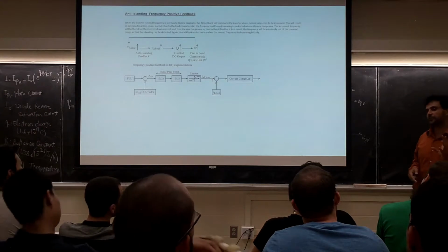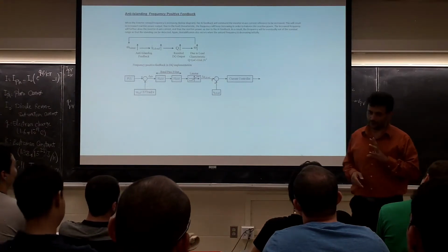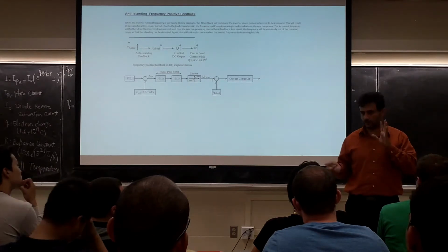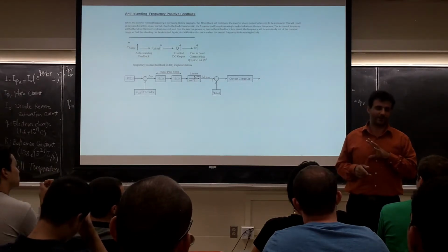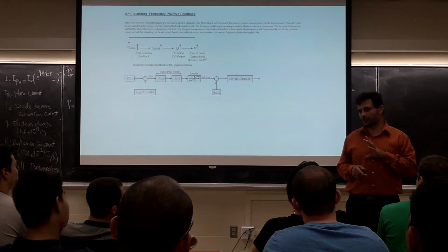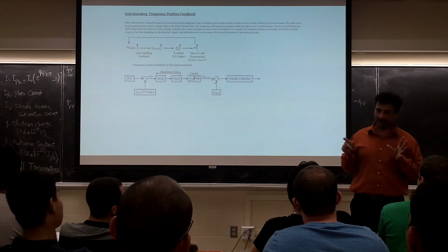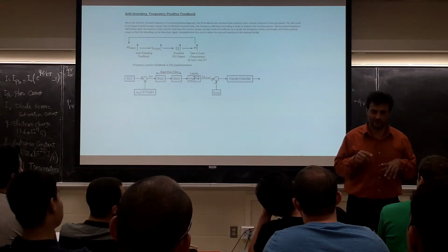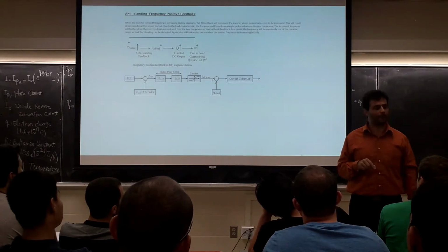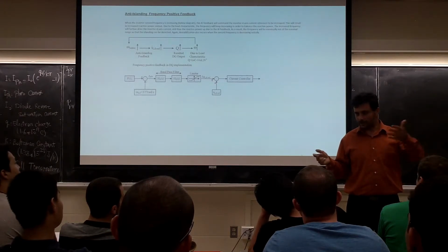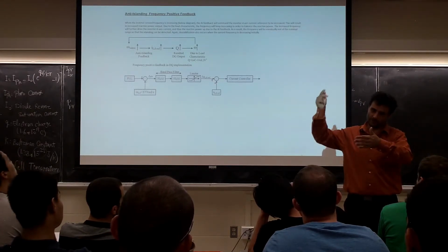But when your inverter is working, connected to the grid, the load may somehow be a capacitor, inductor, or something, a critical load, one that has exactly the resonant frequency of 50 hertz or 60 hertz. What is going to happen? Even if the grid is gone, you are injecting AC, and I'm seeing that voltage, the 50 hertz, 60 hertz.